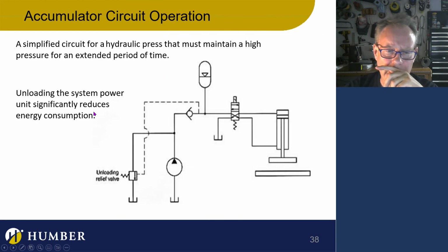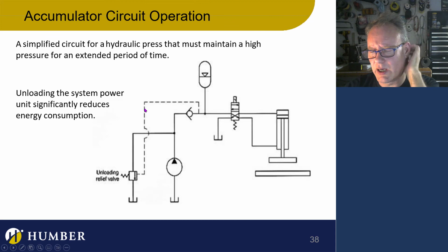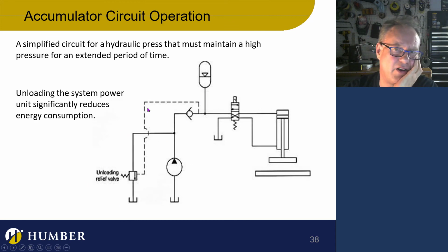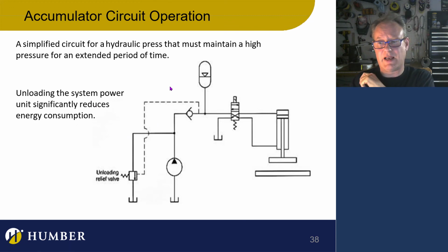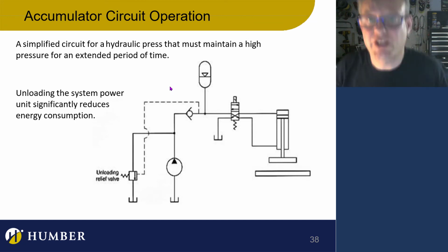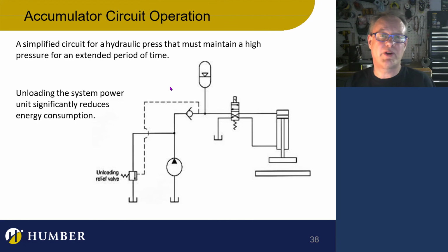Now, it's kind of cool. Talk about unloading for a minute. Unloading is a really cool concept. I'm not sure if you talked about unloading in this course or not. But unloading is essentially an unloading valve. What it's going to do is allow the accumulator to take over from the pump. Or essentially, it's going to say, hey, I got it. Pump, you know what? You can just take a break. I'm going to unload you, and I'm going to take over.